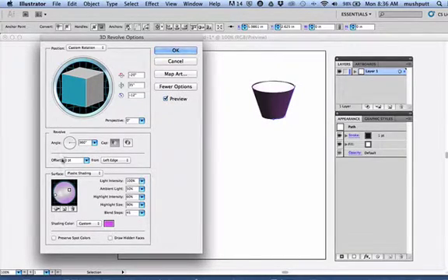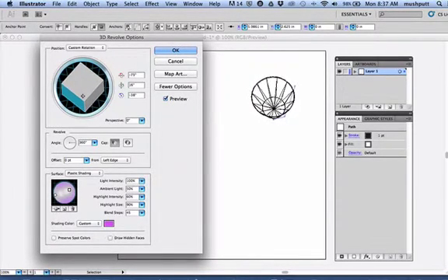Now, offset. Offset is how far this point is when it connects to all the other points rotating around. So what does that mean? Let's just turn this down for a moment so we're looking straight in. Right now, the shape that was revolved comes to a point, and it's this point here. So as the program revolved your shape all the way around, it came to a point in the middle. If we offset that slightly, it should be separating.